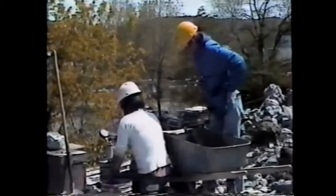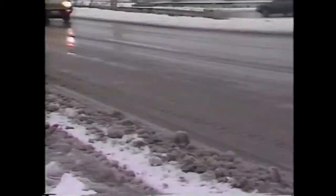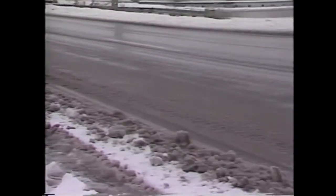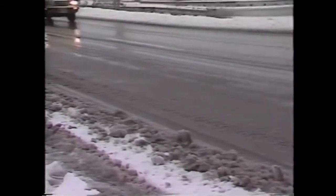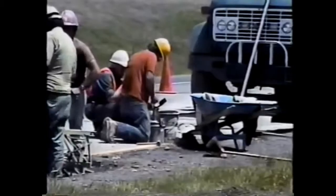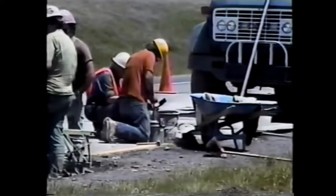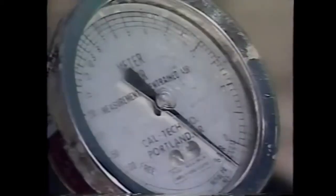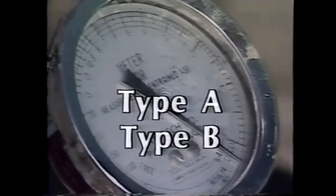The results of air content tests indicate the freeze-thaw durability of concrete. Air-entrained concrete with the specified air content performs much better than non-air-entrained concrete in freezing and thawing conditions. On the job, concrete can be rejected if its air content is not within the allowed range. The most popular method for measuring air content is the pressure method. Two types of pressure meters are available and are widely used. They are referred to as Type A and Type B.